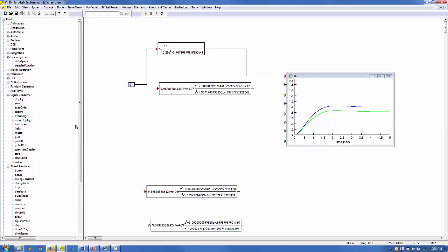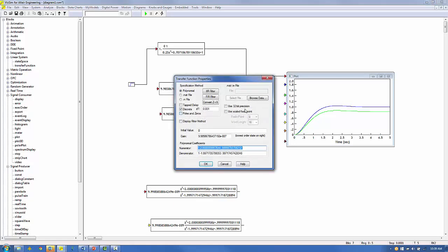Now we'll create the fixed point discrete filter. First, we'll copy the floating point discrete filter transfer function block, right-click to view the parameters. In the upper right section, click Fixed Point and select 8.32 format, and click OK to complete the design of the discrete fixed point filter.